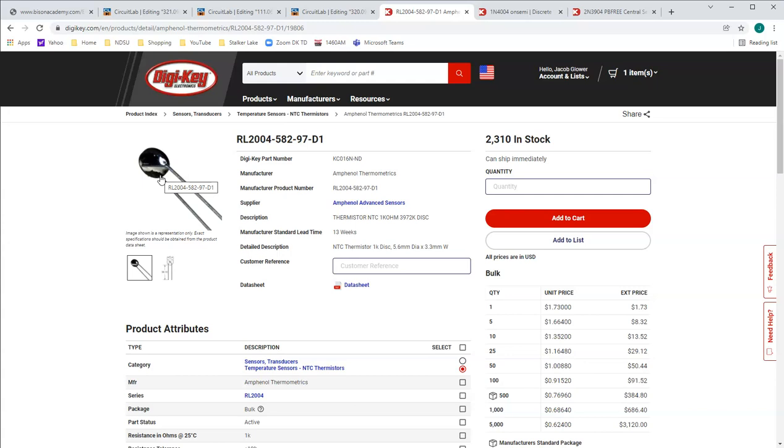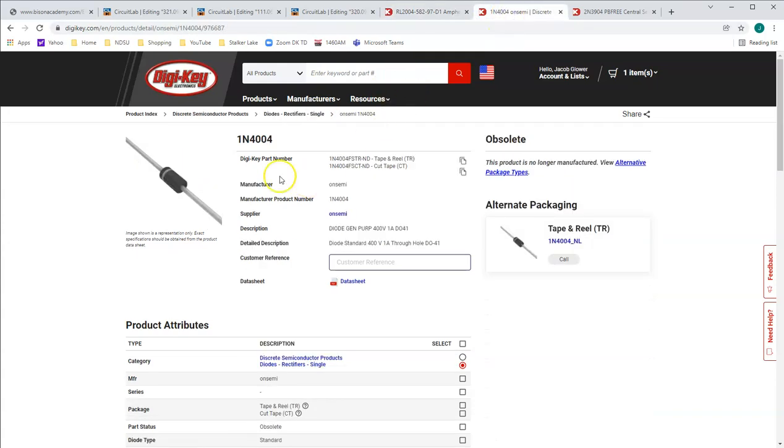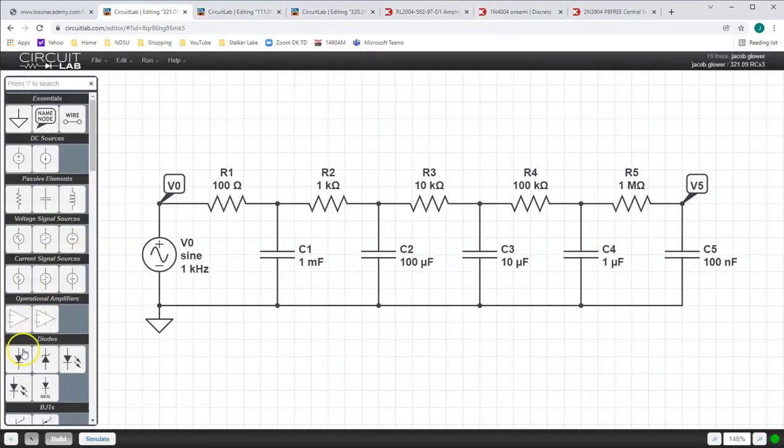If I take two pieces of silicon, put them side by side, and dope them, a thing called doping, I can get N-type or P-type. That's what's unique about silicon. I can get two different types of material. I can get a diode. Diodes look like this, or in CircuitLab, a diode would be this puppy. Diodes are nonlinear elements. They allow current flow one way, but not the other. Very different than a resistor.